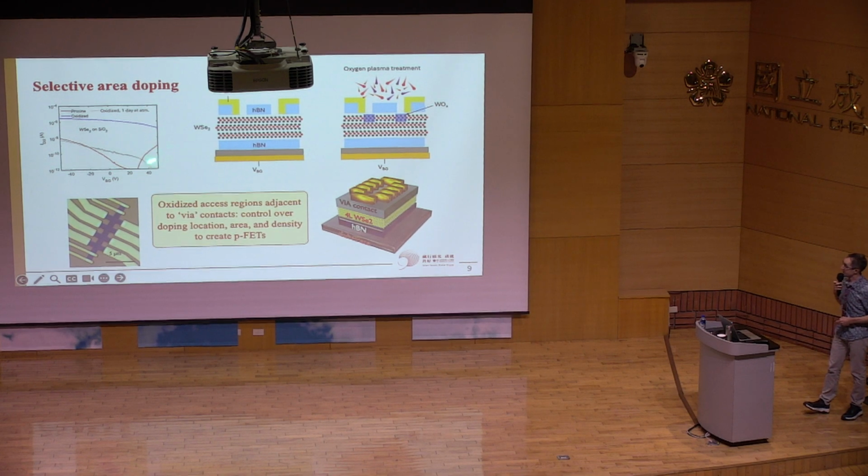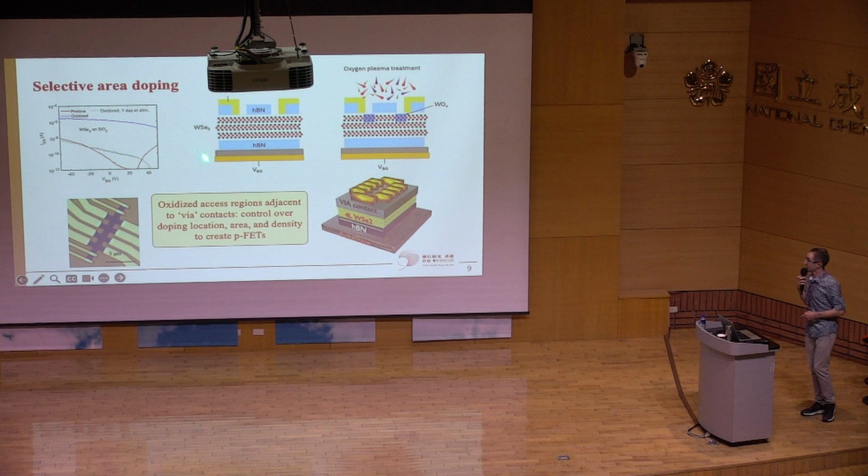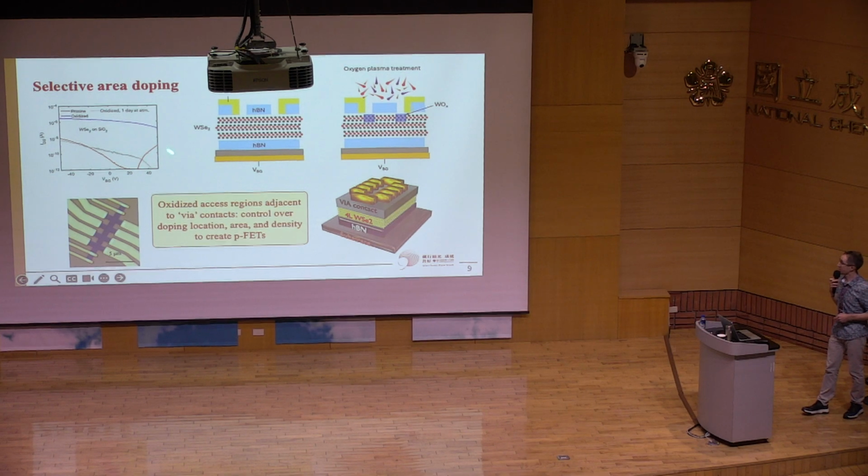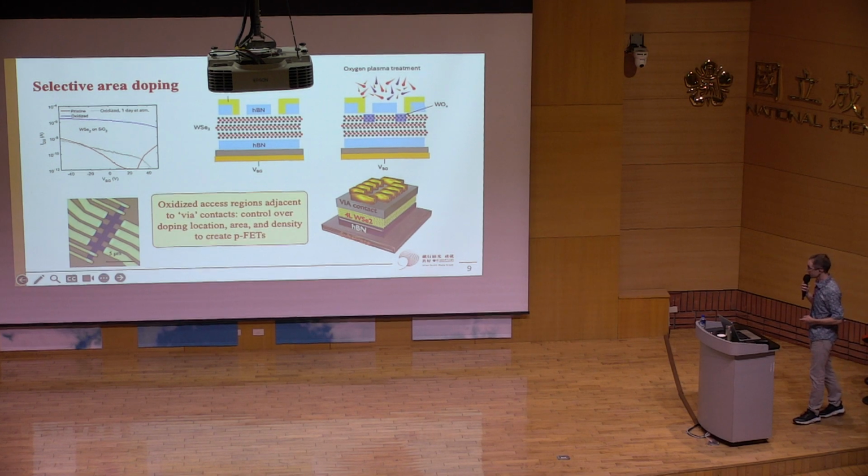The intrinsic properties are this red line here, so you have ambipolar behavior, with slight current in the N and P regions. And then if you oxidize it, you basically get a large current which doesn't switch off within your measurement range, which isn't very useful to anybody. So although it's heavily p-doped, you can't use this to do any FET type operations.